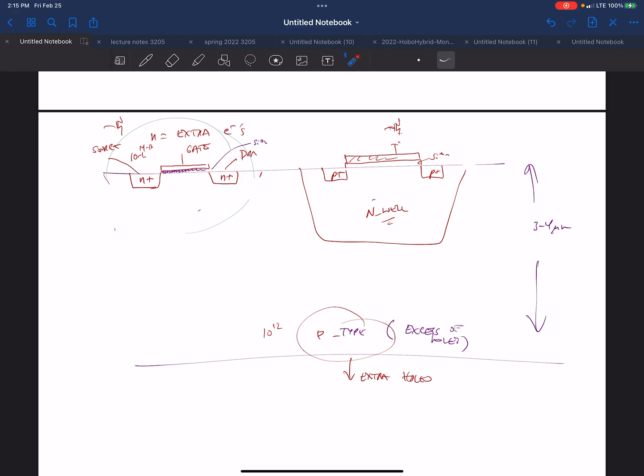I can't put an NMOS transistor up above this one. The connections between the transistors, the metal, are in a stack, and we'll get into that, but all the transistors are in the same planar process. So all the NMOS transistors are in the same substrate. There is no other substrate. They're all connected in this P material.